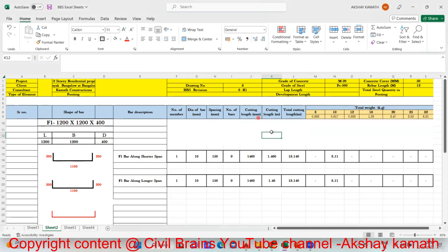So R1. Now what you do, come here, write 5 here and write 5 here. Finish. You see the magic also. I just gave 5 here, and the moment I gave 5, this also automatically took 5 because it was interlinked. Similarly, you see the steel also got changed. It came out to be 40.56 and 40.56. That's the beauty of using an Excel sheet for doing your bar bending schedule.